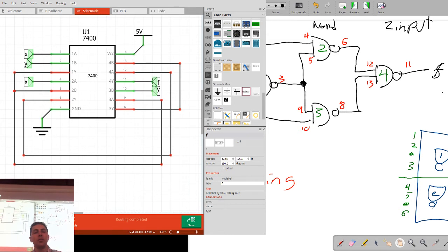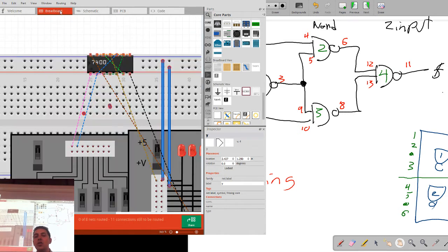So you may ask yourself, why did we draw this schematic when we had a perfectly serviceable schematic over here? The reason is a term called forward annotation. Forward annotation means whatever you put in this schematic, the breadboard will remember it. So see all these dashed lines that have appeared? Those are indicators to you, the designer, that in your schematic you said these two things were connected, so you should probably put a wire there. Because most of my CAD packages are smarmy and snarky like that.